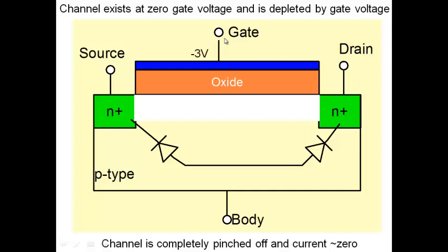It has a transconductance, and therefore, when it has a transconductance, we'll see you can build amplifiers and all of that you can do. Okay. So this is what we call a depletion mode transistor. Again, why depletion mode? Because a channel exists at 0 gate voltage, and you apply negative voltage to deplete the channel and eventually remove the channel altogether.